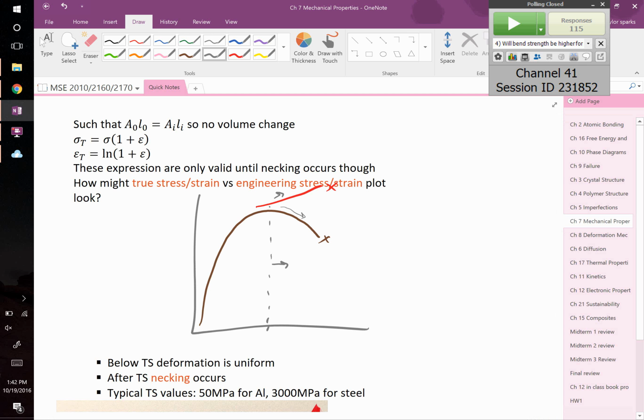If your experiment's running nice and slow, you could sit and watch for necking, and then get your little calipers out and start trying to measure it and hope it's some nice shape that's easy to measure. But because that's hard, it's just not often done. The right way to do it would be to account for that, because that's technically what's going on instantaneously.